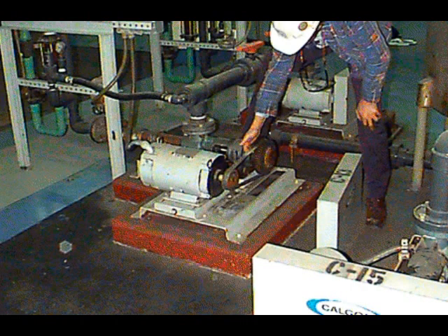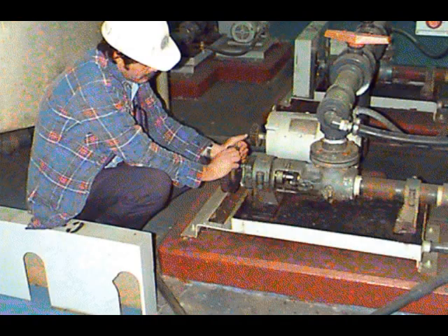The pump will not pump when the motor is running. The belts could be slipping. For this, tighten the belt and apply belt dressing if necessary. The pump may not be pumping because the rotor is initially tight in the stator from sitting idle. To ease it, turn the pump manually 2 full rotations.